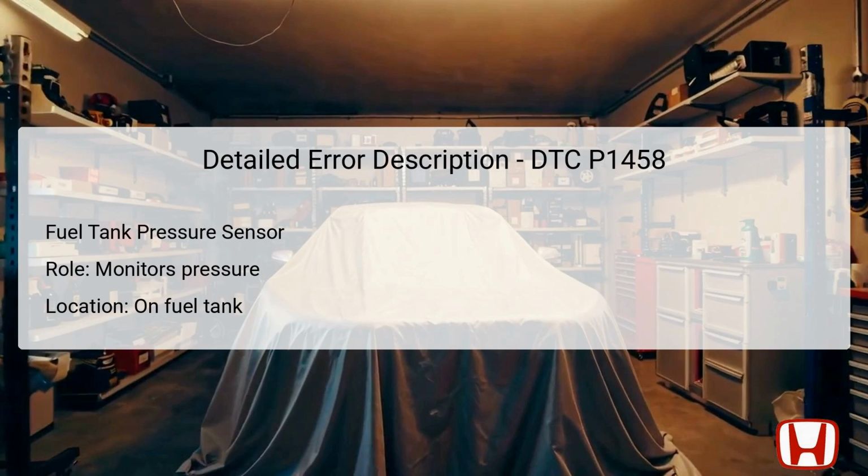The fuel tank pressure sensor is a key component in monitoring the pressure conditions within the fuel tank. Positioned directly on the fuel tank, its primary role is to detect the varying pressure levels that can affect fuel evaporation and gas emissions. This sensor sends readings to the Powertrain Control Module, PCM, which then analyzes whether the pressure levels are within acceptable limits. If it detects abnormal pressures, it flags an issue by storing the DTC P1458.